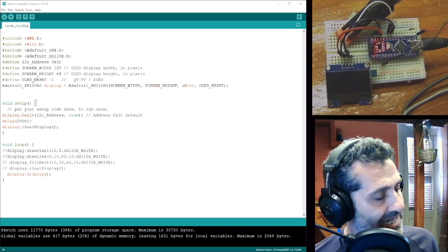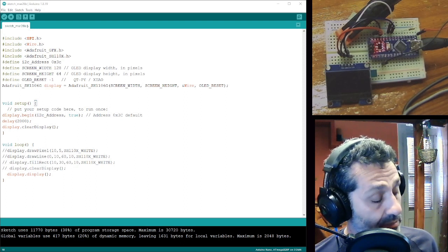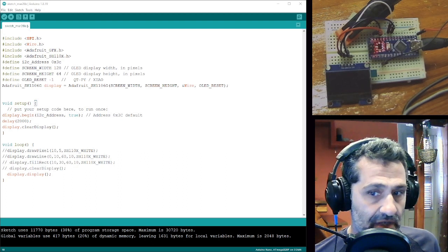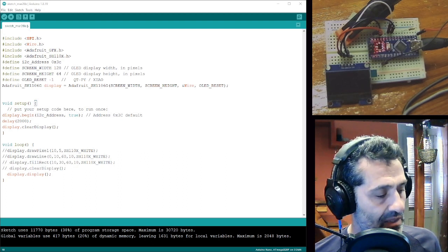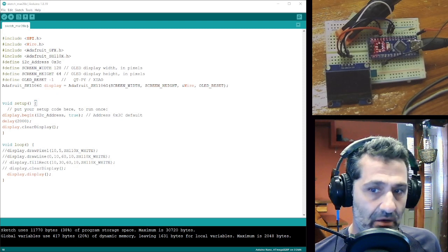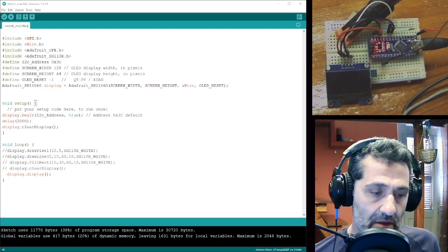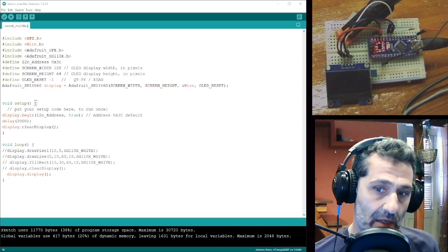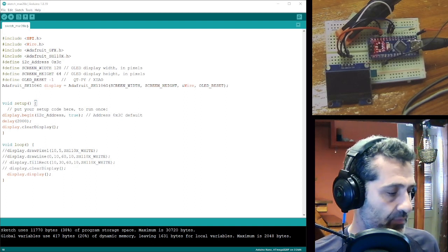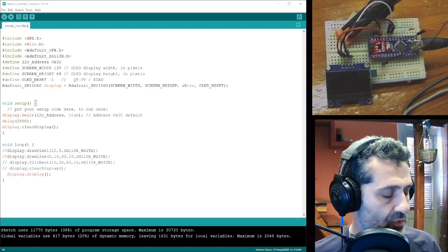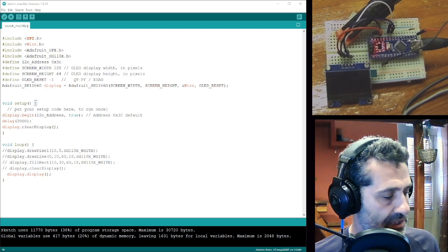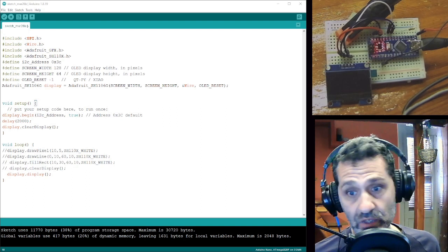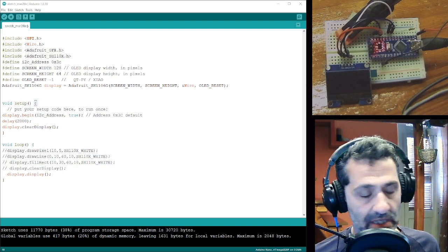The Arduino analog inputs cannot read negative values, and we should be careful when we feed negative voltages to the Arduino analog inputs. There could be some ways to get over this, put diodes and stuff like that, but we would lose a lot of signal if we put diodes.